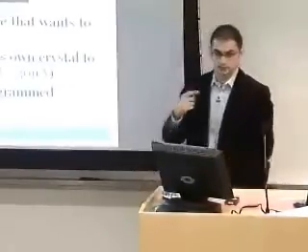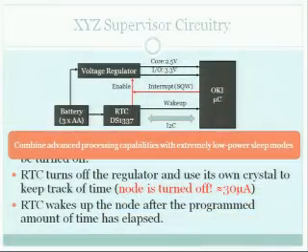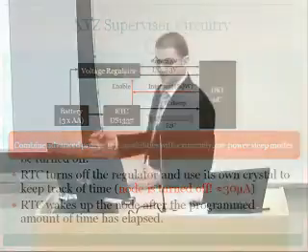In this case, the processor can turn off the whole sensor node, including itself, and then wake up independently. And by doing that, we can have a current consumption of approximately 30 microamps in deep sleep mode. So in that way, what we've actually achieved is to combine the advanced processing power of a 32-bit microprocessor with an extremely deep sleep mode.